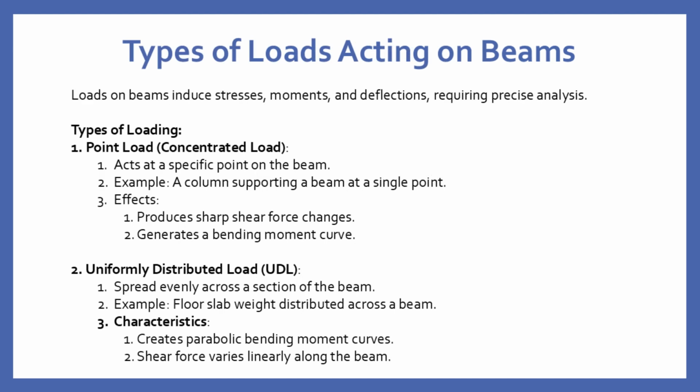Let's discuss the types of loads acting on beams. Beams are subject to various loads that induce stresses, moments, and deflections, which require precise analysis. A point load, also known as a concentrated load, acts at a specific point on the beam, such as a column supporting a beam at a single point.